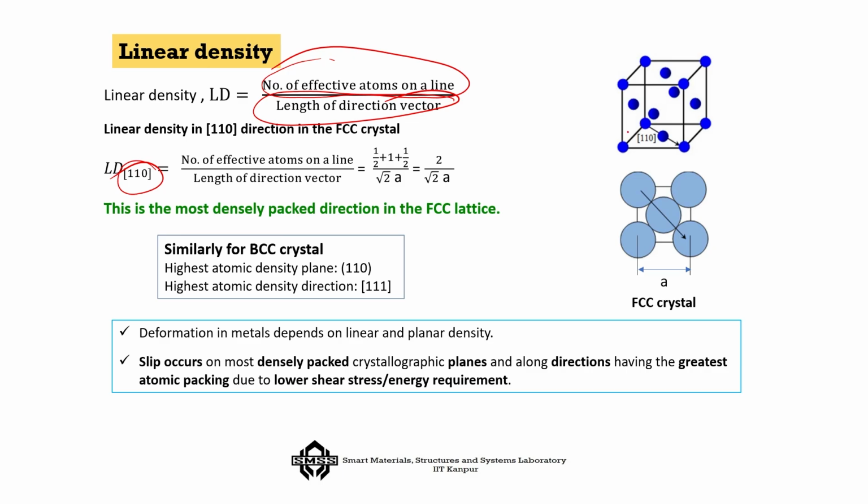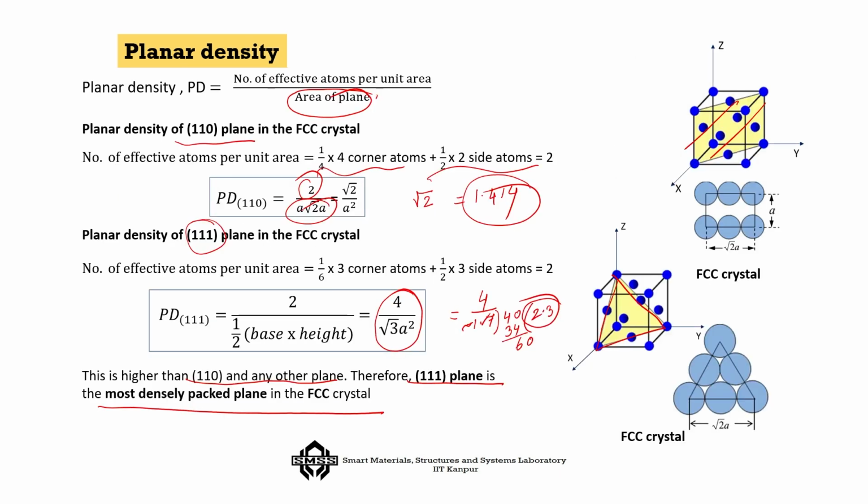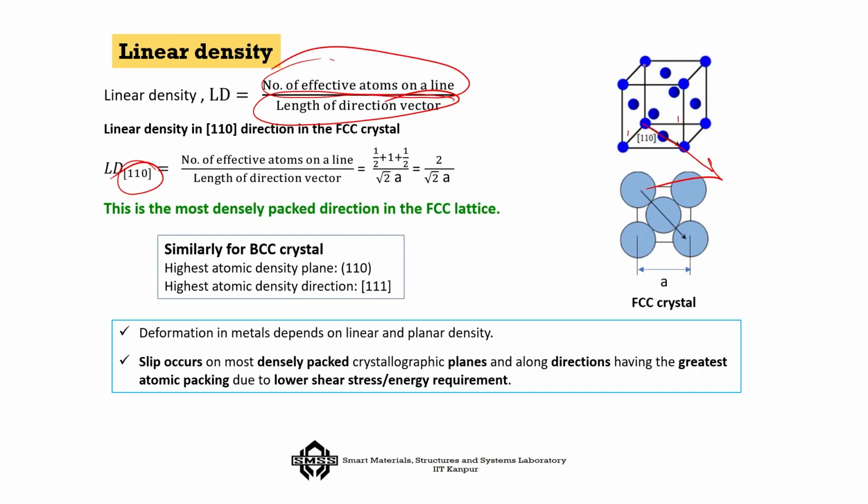that is 110, this line, okay. And earlier we have noted down this plane, right. We have noted down this plane, so that is the 110 plane, okay. But now we are noting down the direction, and this is the plane that we saw is the highest density plane. So, that is the plane, and so that means if I try to draw it here, that is the plane which is the highest density, and this is the direction along which the linear density is the highest. Okay.